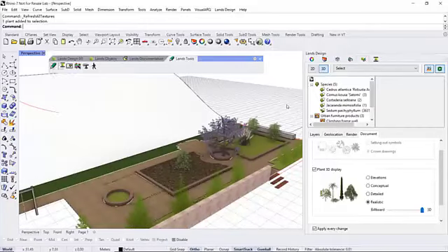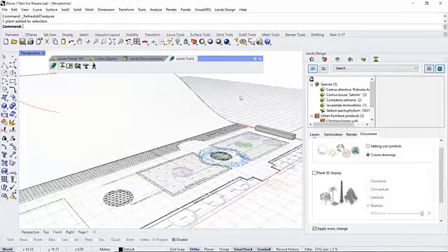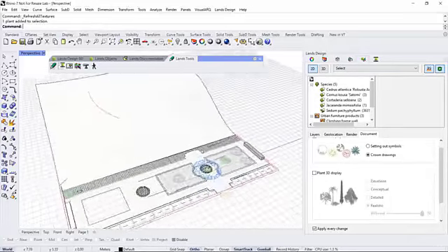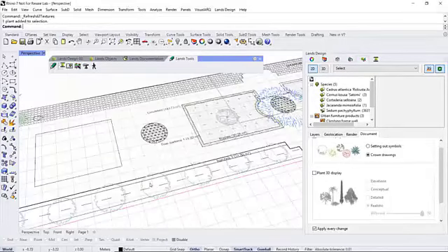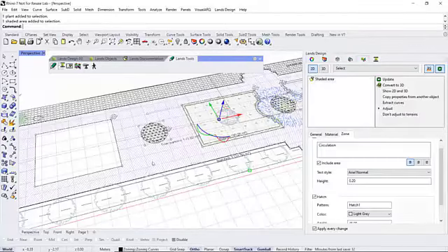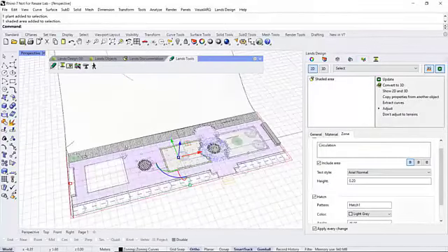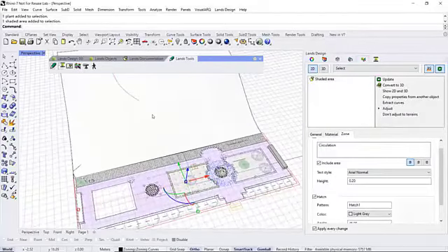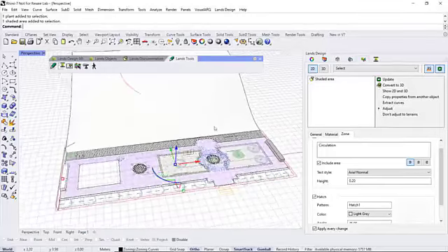In addition to the 3D representation, we can show the objects, the land elements, in a 2D plan view representation. When we select this 2D icon over here, all the elements will show the 2D ground in the case of the plants, but also a hatch pattern in the case of zones, some contour lines in the case of terrains, we'll see later on, and so on.